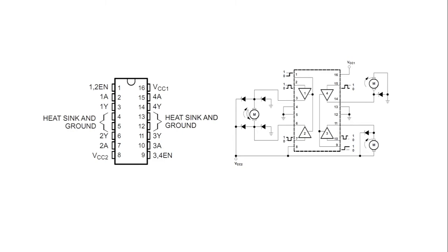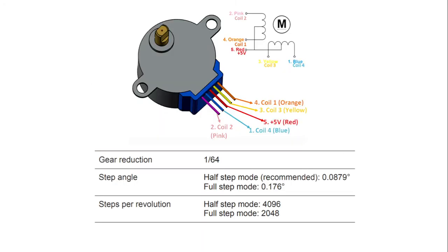So right here we have the schematic diagram of the L293D, just like our last experiment number 1. We used this for the control of the DC motor, and as you can see on the right side, we have this internal schematic of the L293D, but we use the left side, which is the bidirectional DC motor control. But for this application, we will be utilizing the unidirectional configuration, or at least that configuration, for controlling 4 of the inputs of the stepper motor.